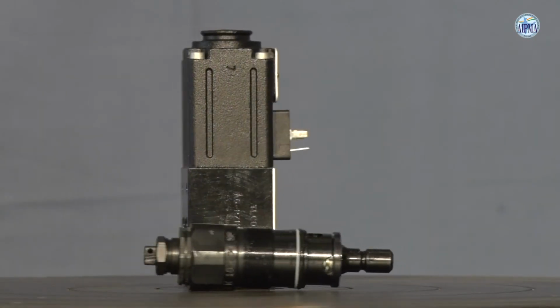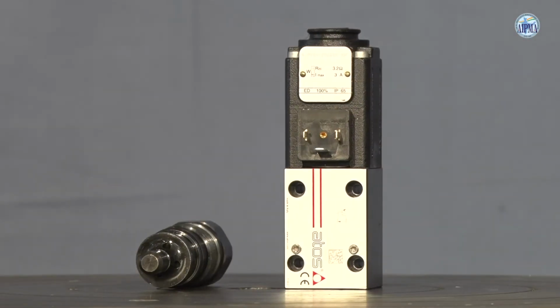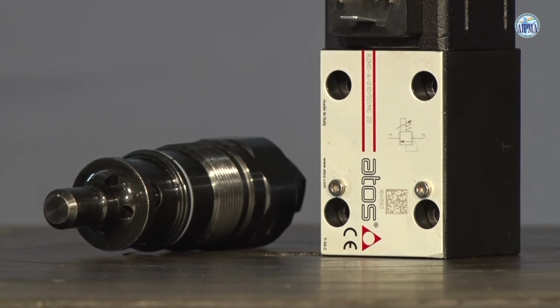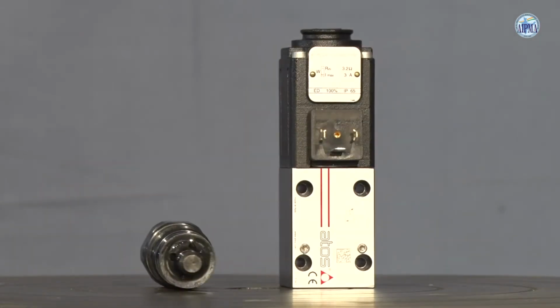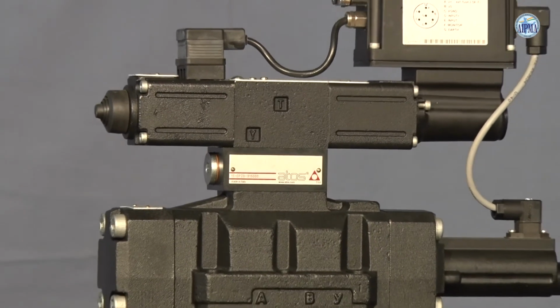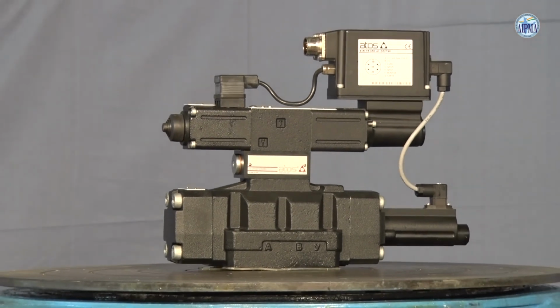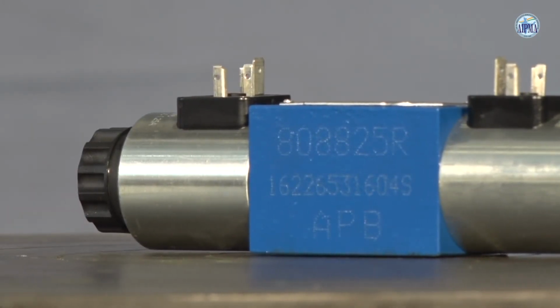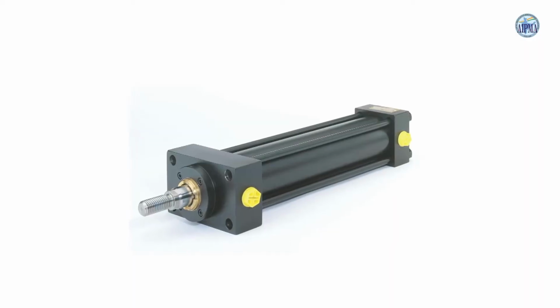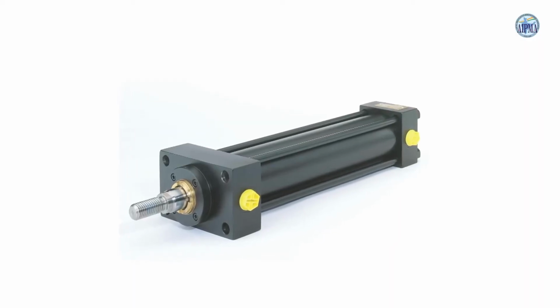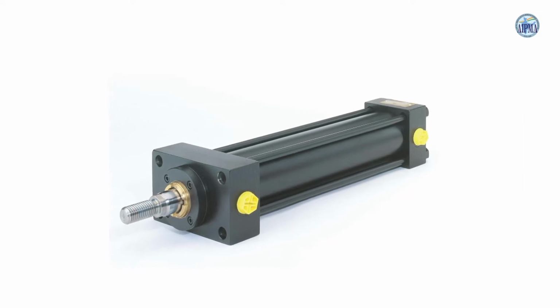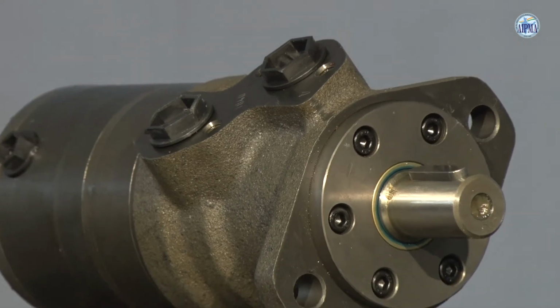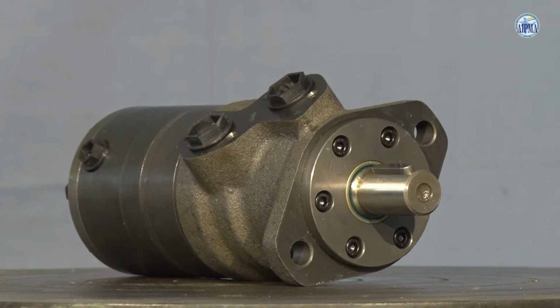Major components of hydraulic system. Pressure relief valves are used to limit the pressure at specific limit. Flow control valves are used to control the speed of actuators, for example cylinders, hydromotors. Directional control valves are used to direct oil to the actuators. Cylinders are used for linear movements, for example clamp open or close, injection forward or retract. Hydromotors for rotary movements, for example screw rotation, mold height adjustment.